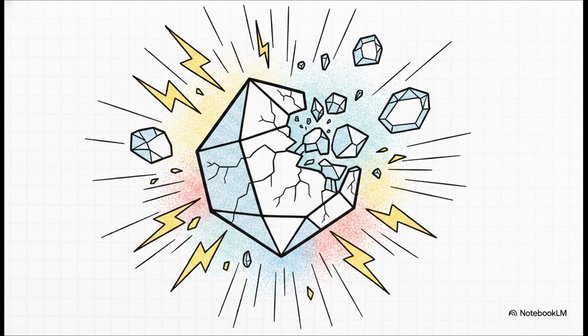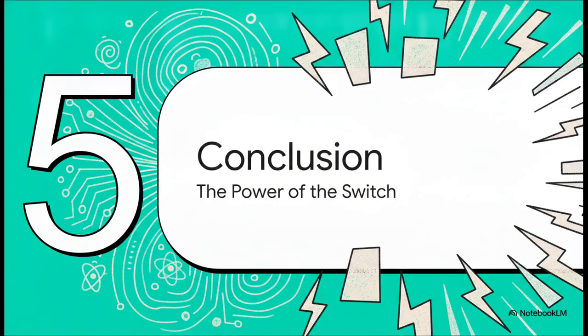Of course, at the end of the day, this is still a delicate physical piece of silicon. Datasheets will always specify maximum transistor ratings for a reason. If you decide to push the voltages or the maximum collector current or the total power dissipation beyond these strict limits, well, you're going to permanently damage or completely fry the crystalline structure of the transistor. So, respect the datasheet.